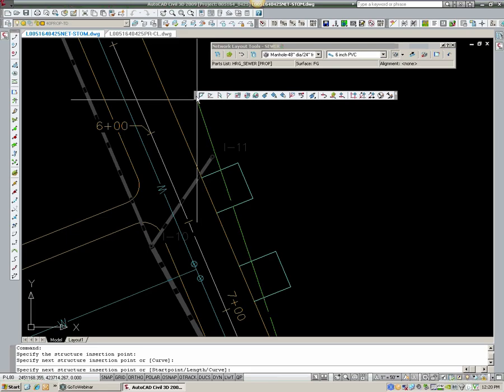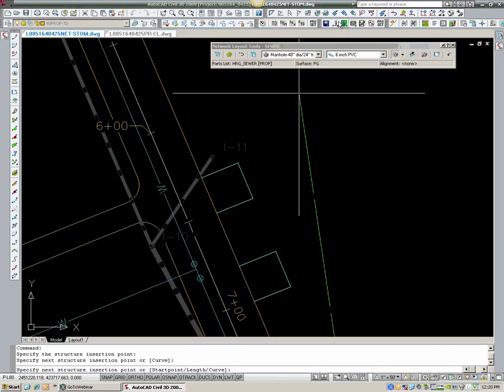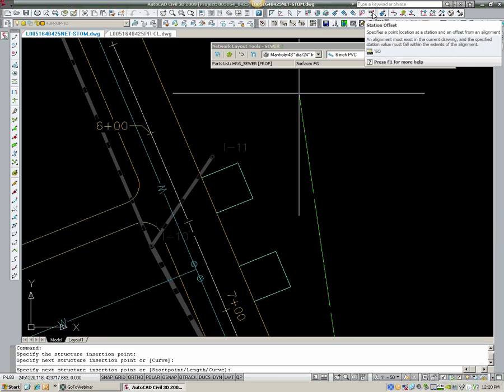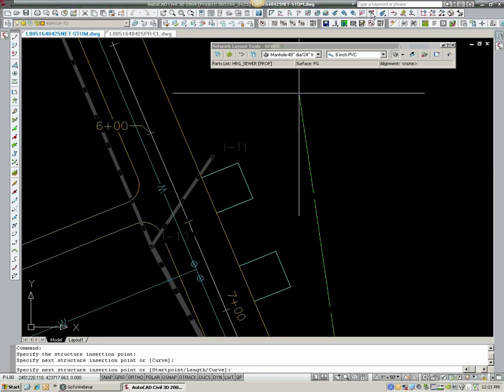I'm still on the tool. I'm impressed with that. And once you have that tool up, what we want to use here is a station and offset transparency command. So in Land Desktop, you might have been familiar with this. It had transparency commands, not as many as Civil 3D, but you could hit the little caret key side of the enter button on your keyboard and type in if you knew the codes. And here it's sort of the same thing, but you can actually pick them from a button.